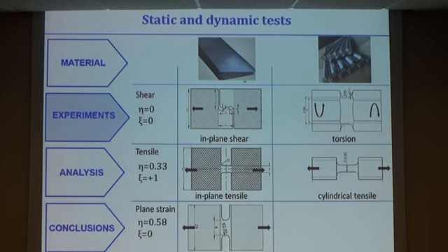So we developed a plane shear sample geometry. By applying a tensile load, we concentrate shear stresses in this region of the material. What is very special for this geometry is that we have slightly asymmetrically positioned notches. During elastic deformation, we have a slight rotation of the shear region, and as soon as we come into the plastic region, we have a fully aligned shear region, so that we have very low triaxiality, as I will show.